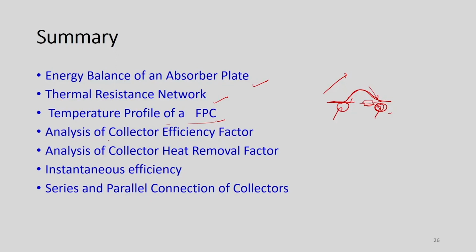So, we have analyzed the collector efficiency factor as well as collector heat removal factor, and also we have understood the importance of these two factors in designing a flat plate collector, and also we have studied instantaneous efficiency and collector efficiency, and also we have studied the series and parallel connection of collectors and under what condition we can use series connection and under what condition we can use a parallel connection. Of course, we can combine both as per the requirement of the volume of water required and